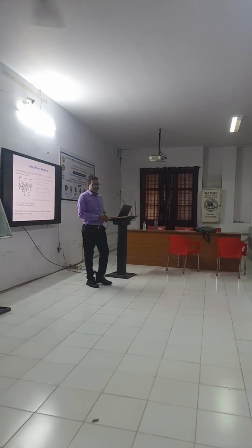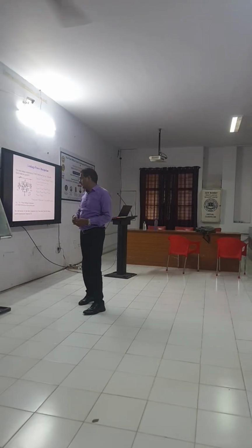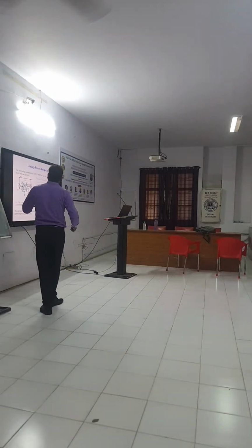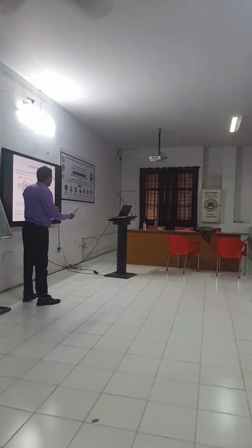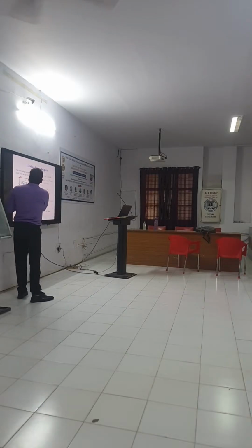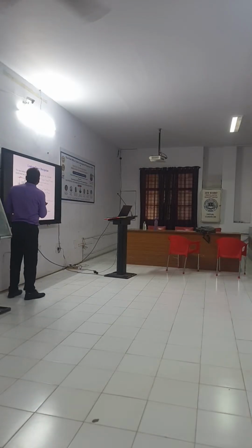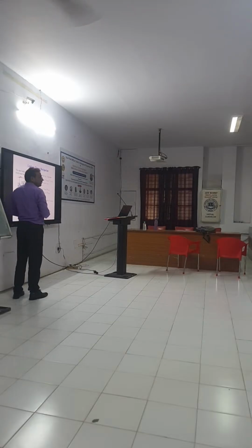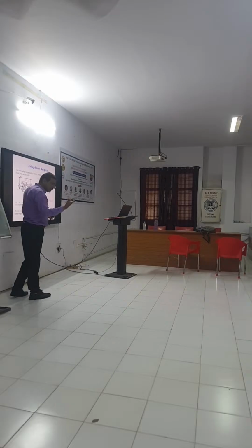Then leakage power. Leakage in previous work I didn't mention very well. Leakage, just the formula we see here. Actually, leakage means we are not reading and writing. That means this is off, this is off. If this one and this one are off, how can you make this off? We have 0, so this is off, this is off. But still power dissipation, still leakage current is happening.